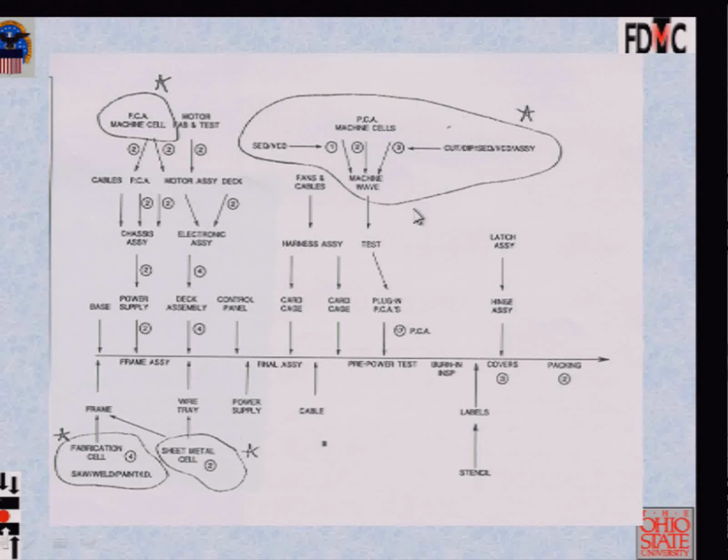And this is again what Ohno said in his book, Toyota Production System, that you should build the facility and schedule the facility as per the logical building of the product from its components into its sub-assemblies into the final product. And so appropriately then you will say, well, this is how I will design my sheet metal shop, this is how I will design my machine shop, my injection molding shop, and so on. So if you look at Toyota's San Antonio facility, this is the main assembly plant, and then they've taken these major modules and put their key suppliers right around the main assembly plant. It's logical. It just makes complete sense.